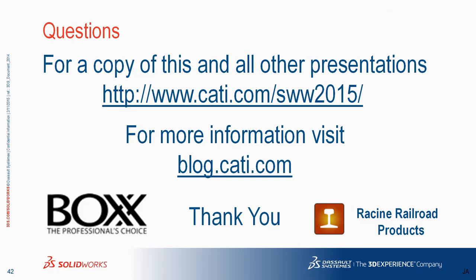There was actually a multi-body class yesterday that was talking about the features. If you have a funky geometry on the face and all the features, say the cuts come from that funky geometry, if you flip and put the features first and then do the cut for the weird geometry after, it will change the rebuild time exponentially faster. Like from, say, 5 minutes or 1 minute to 3 seconds.